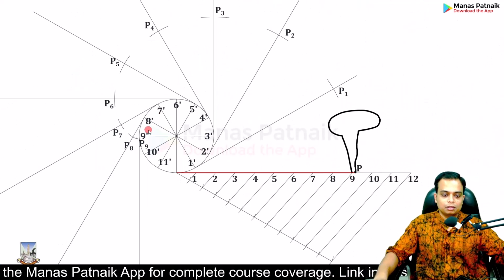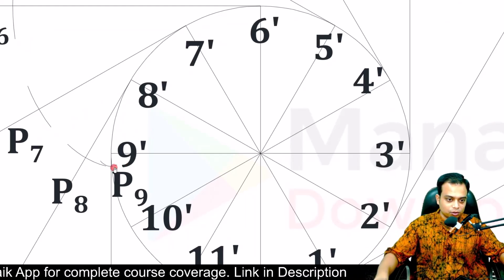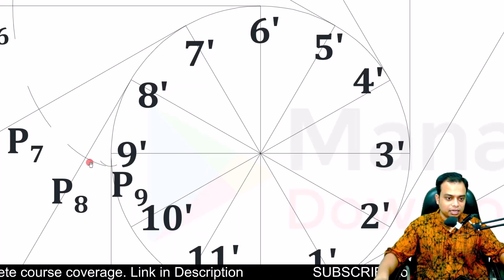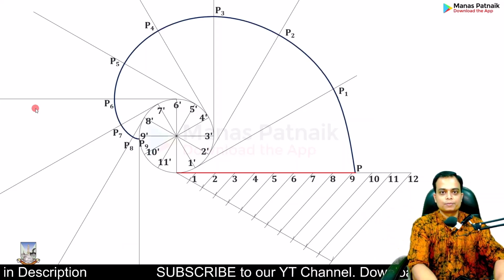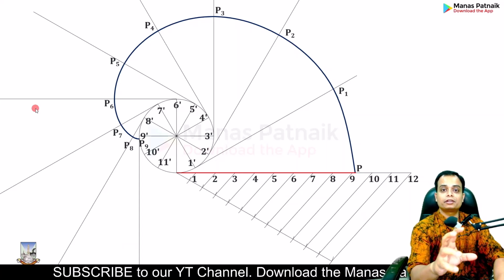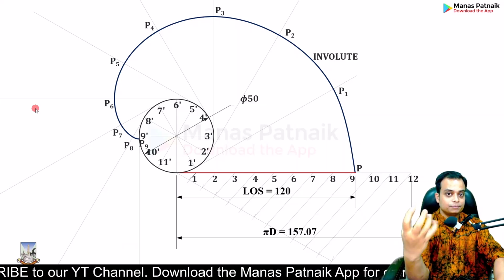And yes, now you just need to join all the points in proper sequence. Start from this point on the periphery of the circle, then on this tangent through 9 dash, and then on this P8, then P7. And once you join all of these points, this is going to give you a beautiful curve, popularly known as an involute. And if you want to see how the construction work looks like, how you need to dimension, this is how it would look.